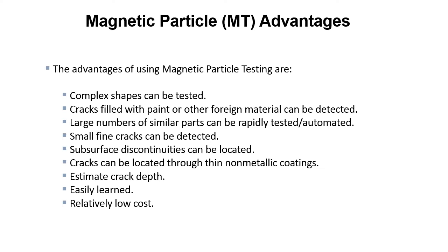Subsurface discontinuities can be located. Cracks can be located through thin non-metallic coatings. Estimate of the crack depth, easily learned, and it's a relatively low-cost system or process.